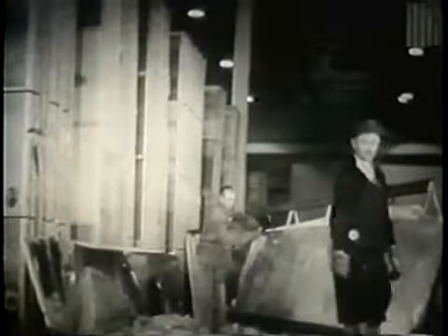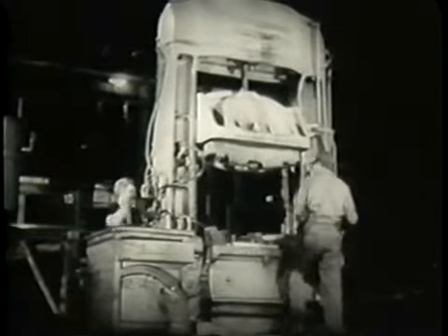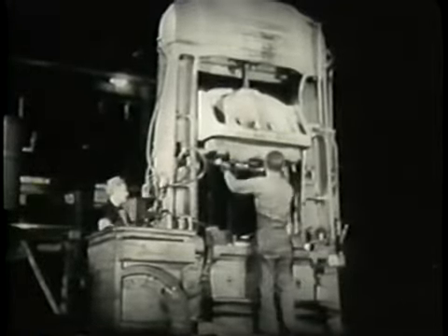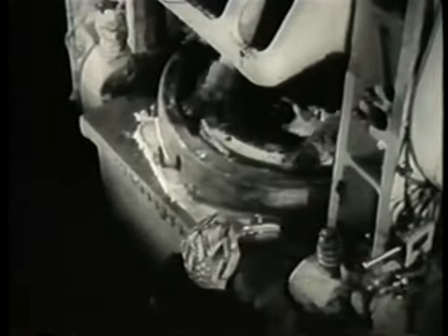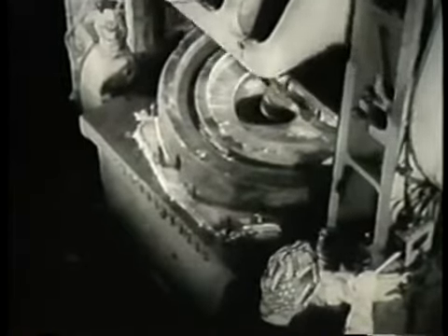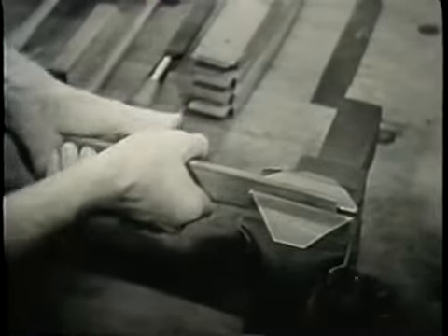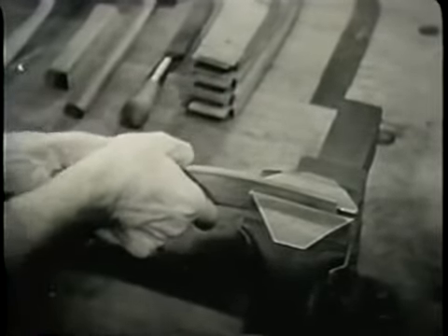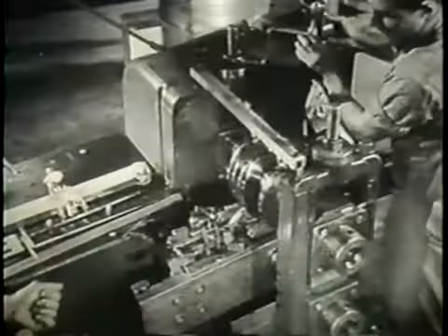The primary function of the various forming methods is to convert the aluminum alloys into desired shapes. Strain hardening accompanies these cold working operations, and in extreme cases, annealing between operations may become necessary. Some forming operations require fully annealed or soft material. Operations such as bending may be performed by hand or by machine.